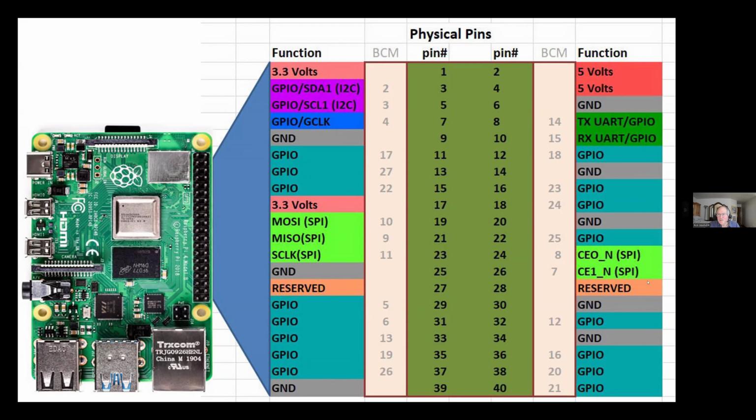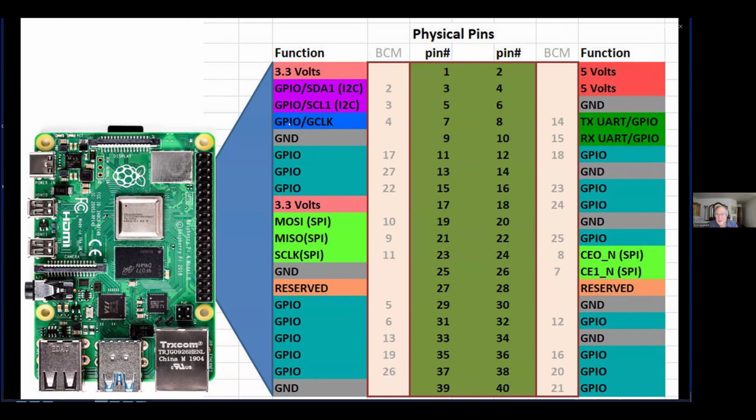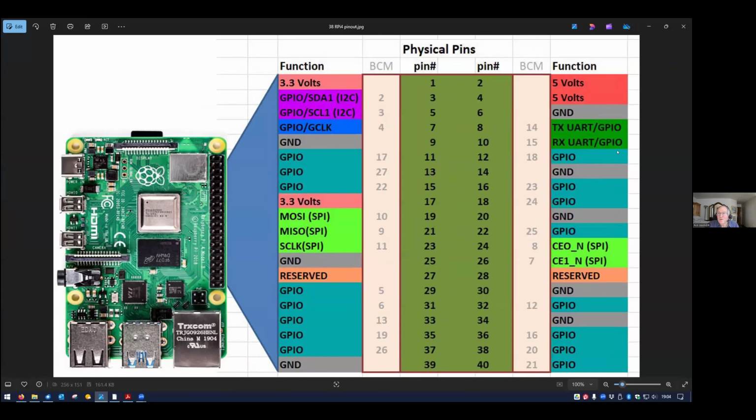And let's see, these are auxiliary on that. Other things, all this GPIO just means that's general purpose input or output. You can either input a 0 or a 1 or output a 0 or a 1. So if you want to do 8 or 16 bits, I think there's 16 total. Some of them are dual purpose. So this can either be GPIO or these things, completely configurable. So this is a world of input output, and you can do a whole lot of things with that too. Okay, that's all I wanted to show from my photos.